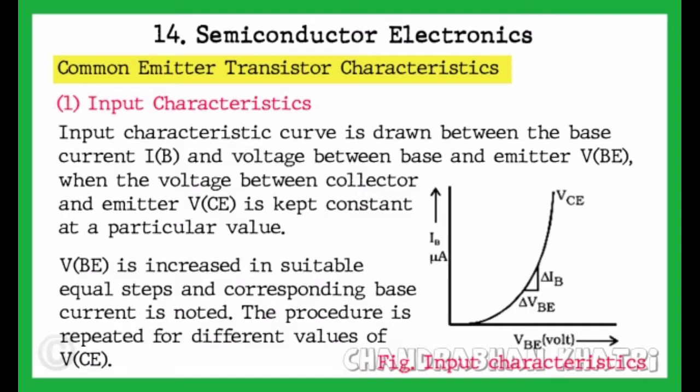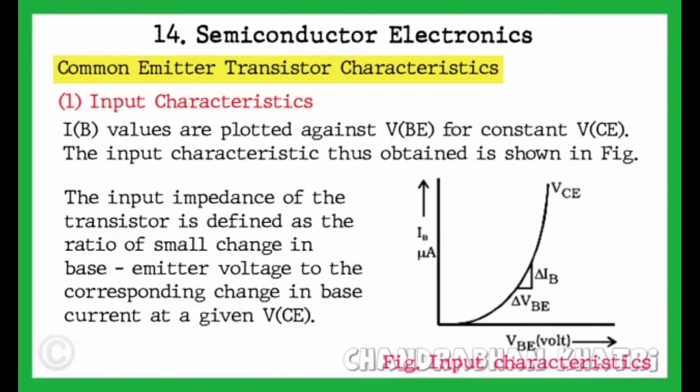The procedure is repeated for different values of VCE. IB values are plotted against VBE for constant VCE. The input characteristics thus obtained is shown in figure.